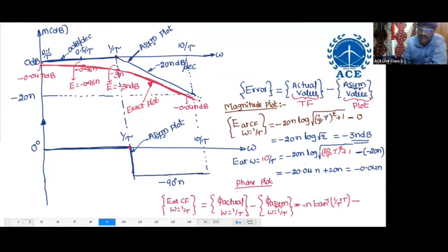0, or it may even take minus 90n also. Better to take 0 for example, 0 degrees. Tau cancels. What is the answer? Tan inverse of 1 means minus 45 degrees n. Error equals minus 45 degrees n. In case you take asymptotic as minus 90n, you will get plus 45 degrees n. Whatever it is, it is a midpoint.